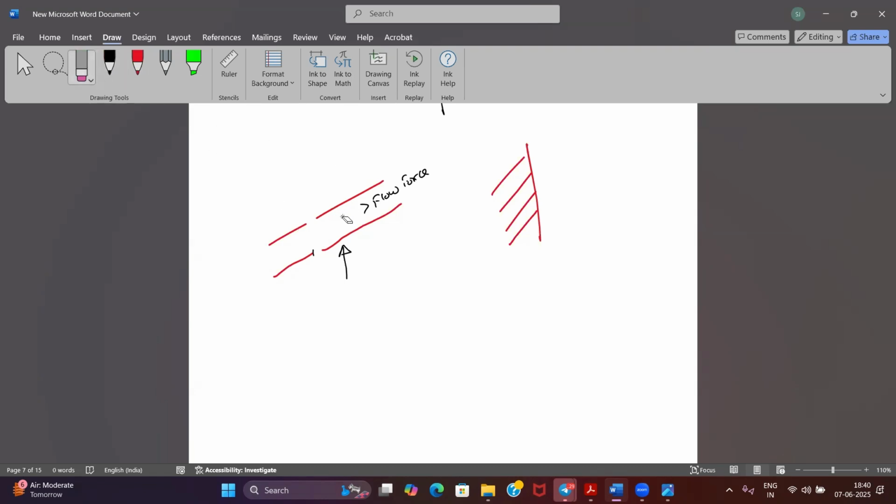No sir, centrifugal force is not acting? Sir, it will act. The purifier is running at 10,000 RPM everywhere. Yes, sir. Centrifugal force is acting, isn't it? Yes, sir. And the force of flow. Now this throughput is not there. Now I have a centrifugal force also. It is always horizontal, right? Horizontally outward, centrifugal force. Yes, sir. Radially outward.